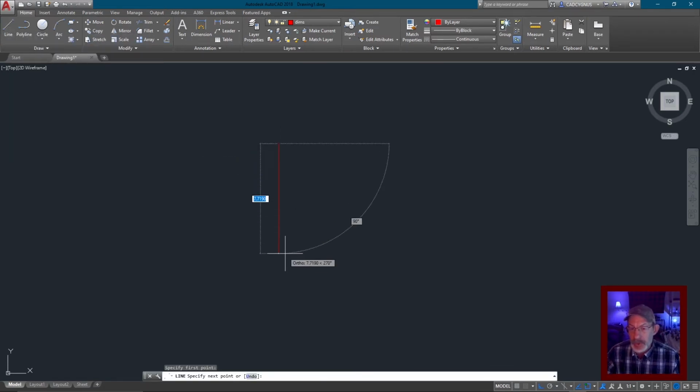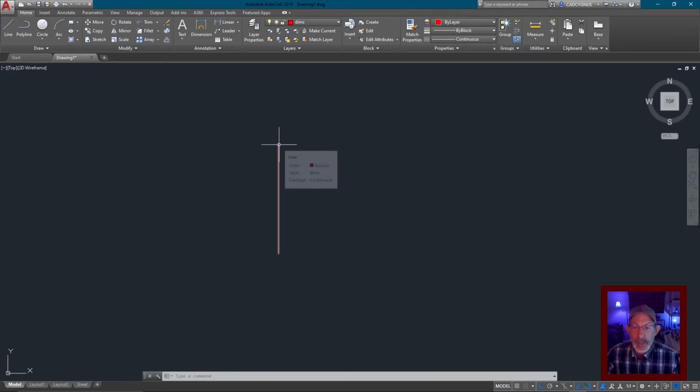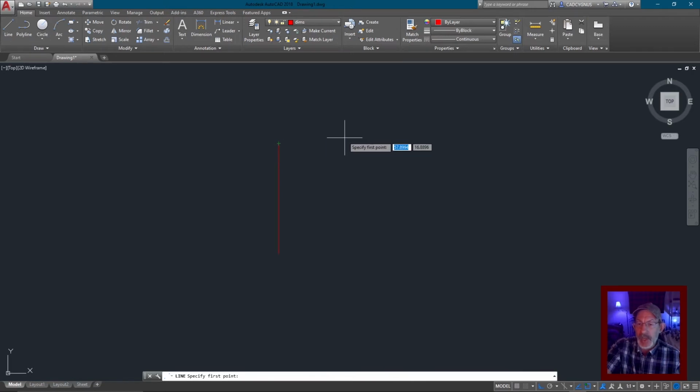So let's say I'm drawing a straight line. And then I want to draw another straight line as you saw me before, but I don't know where to really draw it from. But I want it to be starting at the same point. Well, if I have this icon on here showing reference snap, I can hover over that line, right? I can activate my line, hover over it, see how the cursor turned to green, and I can drag it over and see I'm on the same line as the other line. And I can actually start that line at that point.